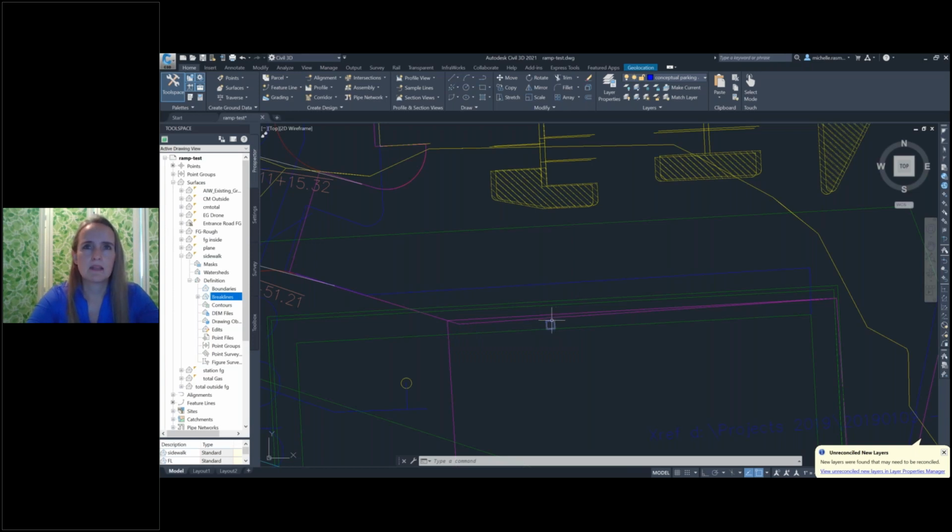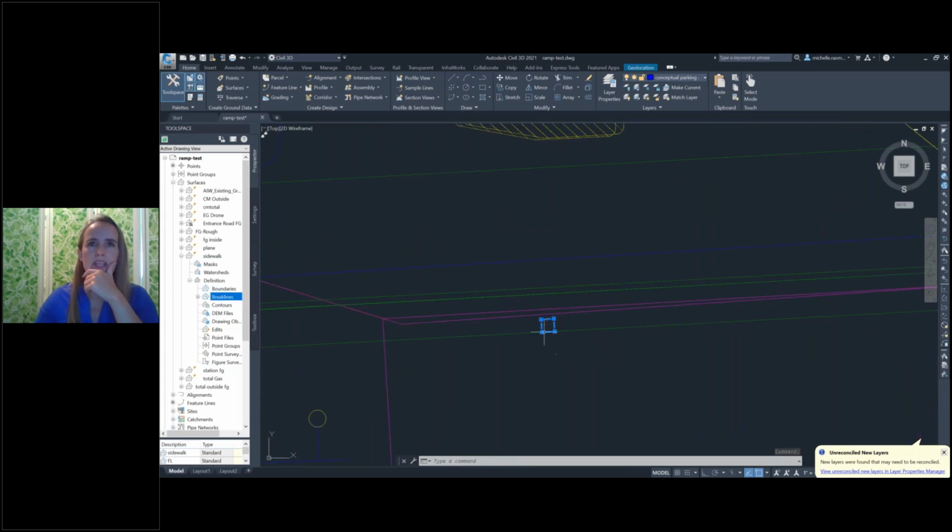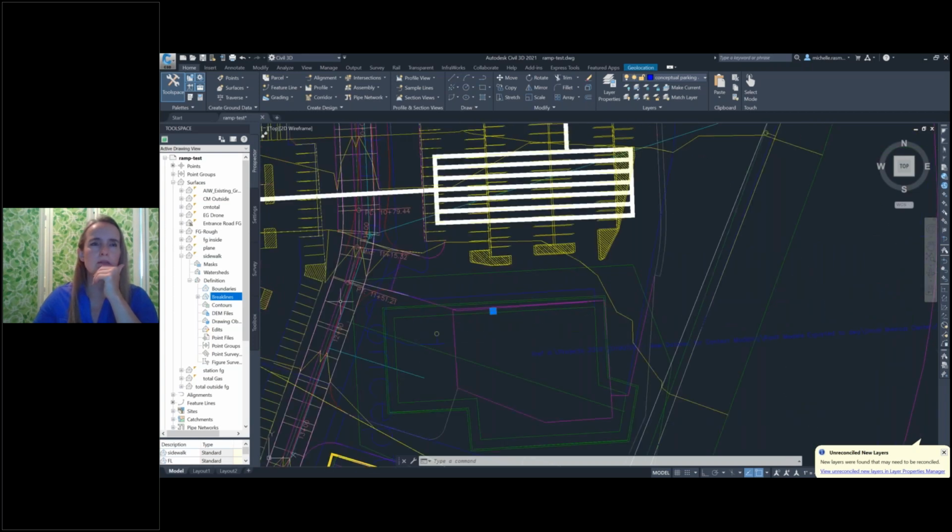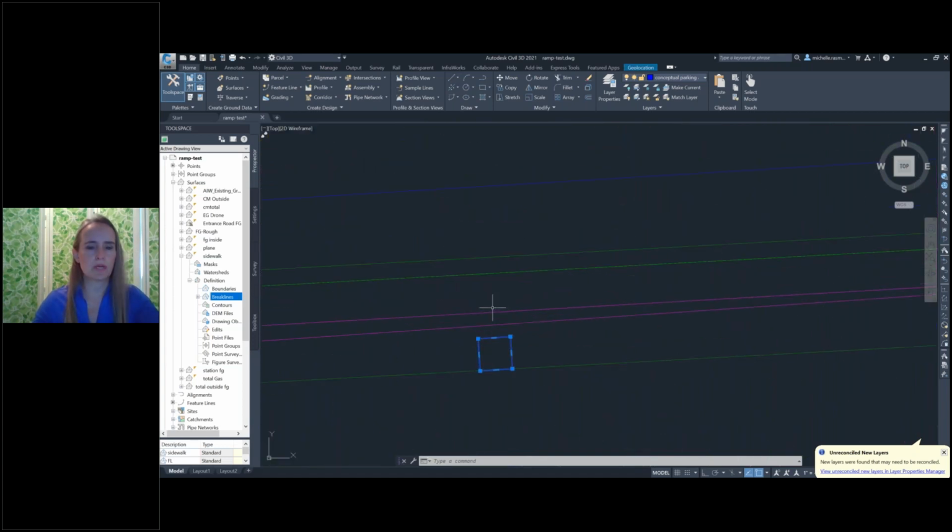So here is my little square. That's my transition point. The nice thing is this one, we're coming straight out the door and then going down the ramp. So I don't necessarily need that, but what if they came in from this access over here and came up the sidewalk and then had to transition and go down to there? Easy enough, right? And so I am going to leave that square in there. That's a 3-foot square just for that transition point that we saw in our standard.